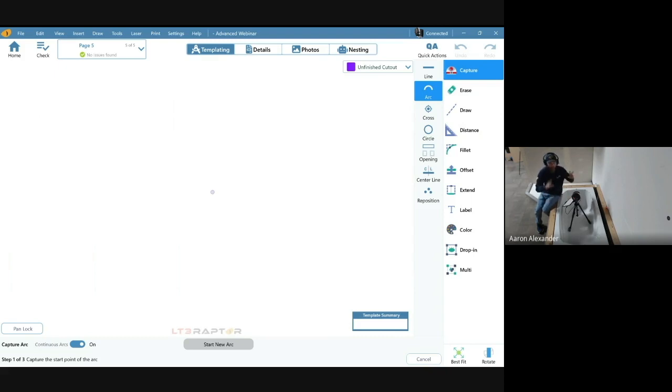When it comes to scribing something like this, if you don't hit the tangent, it don't matter how often. If you shot your point every 2 inches going all the way around this thing, you could miss every tangent and have bad information. Okay. So in this, I'm going to try to actually keep it as simple as possible. I'm going to shoot the least amount of points as possible to create this shape as pretty as I can get it. And I'm going to use the software to see if I hit the tangent.